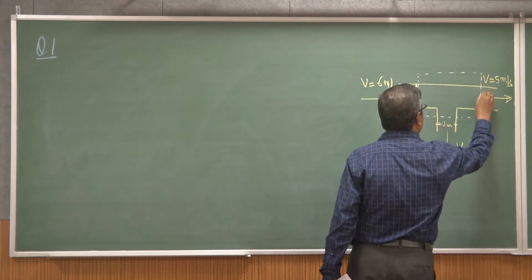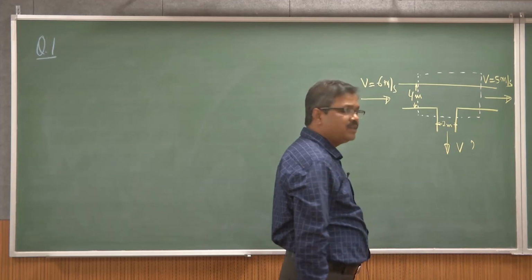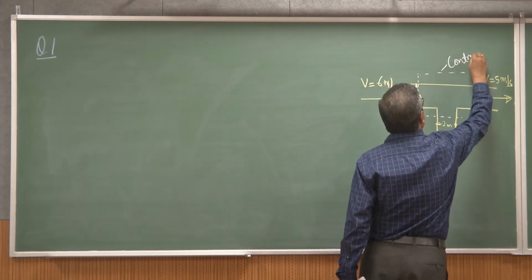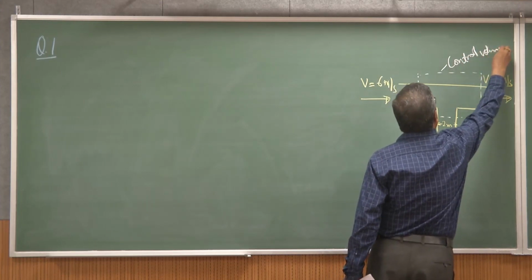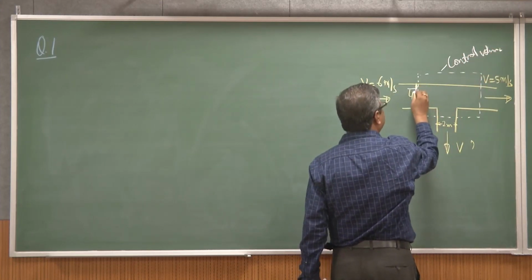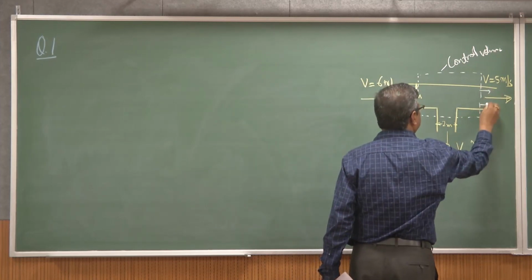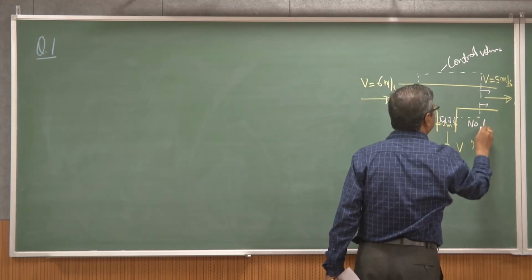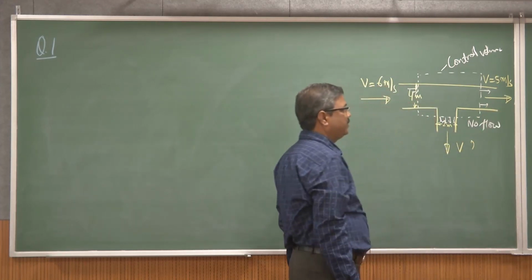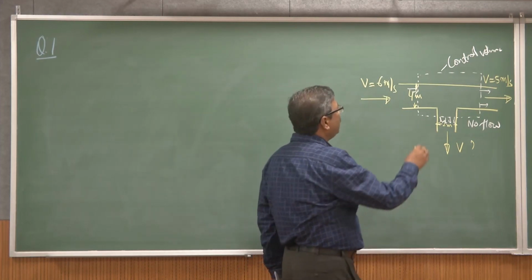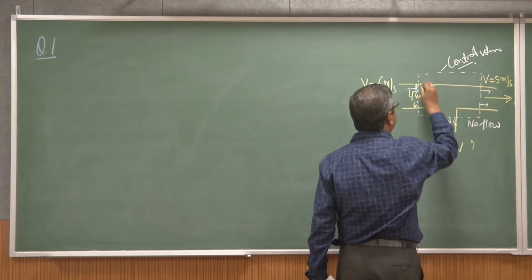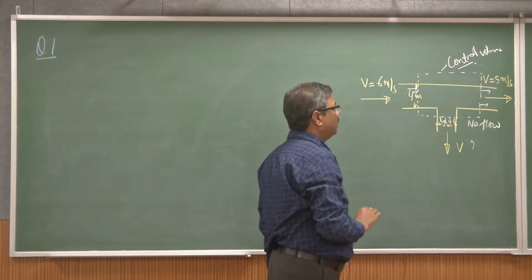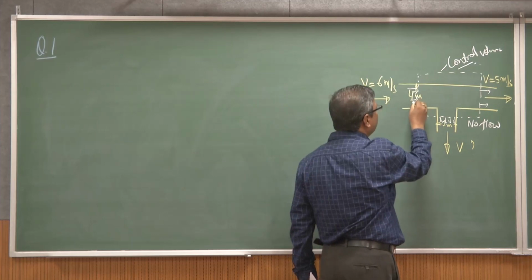From this control volume, you can identify the inflow regions, the outflow regions, and where there is no flow. We should identify these. So once you sketch the control volume, sketch the control surface, identify the pressure on the control surface and the flow directions.